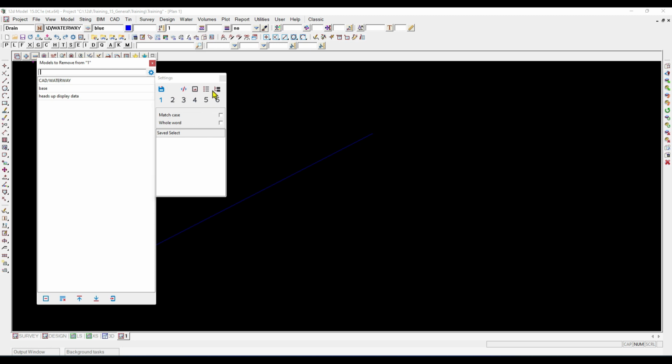More often than not, you'd be either using the path or the tree, and so if I want to go back to tree, I can simply go and click that tree icon at the end, and we're back to our object tree viewing option. These numbers down the bottom, they represent the number of levels of tree you can view. So at this stage, number 1 is blue, so that's what's selected, and you can only see the folder here. But if I go and click on 2, automatically now any folder will be open to the second level and you'll be able to view what's there.